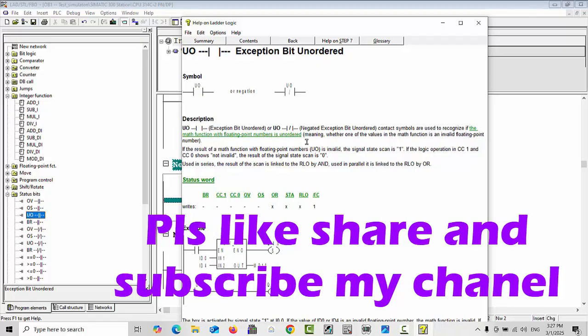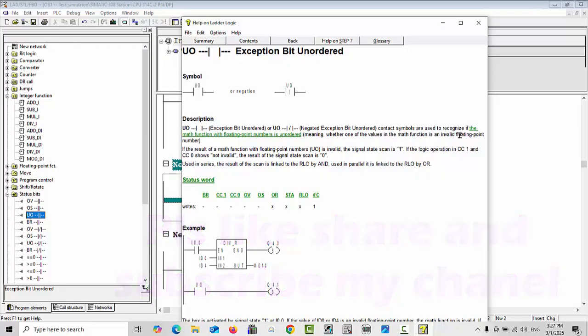What it says: the negative exception bit unordered contact symbols are used to recognize if the math function with floating point numbers is unordered, meaning whether one of the values in the math function is an invalid floating point number. If any value is invalid, meaning infinite numbers or similar, then this status will be activated. This exception bit unordered stands for a status bit.